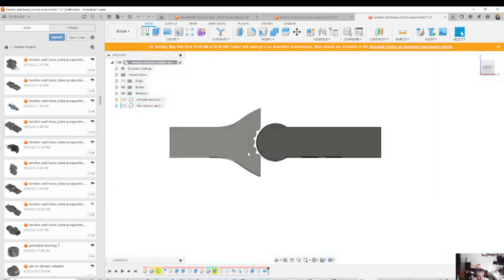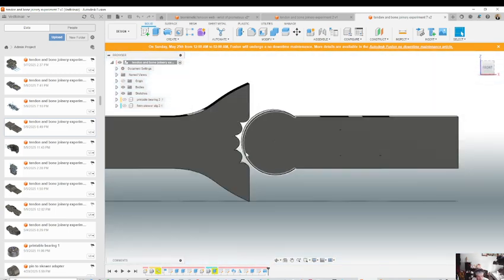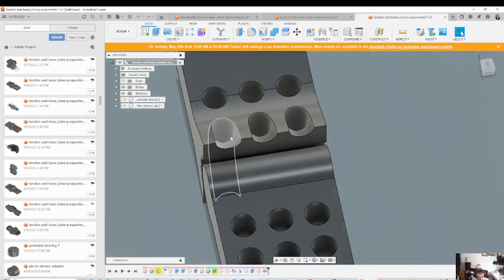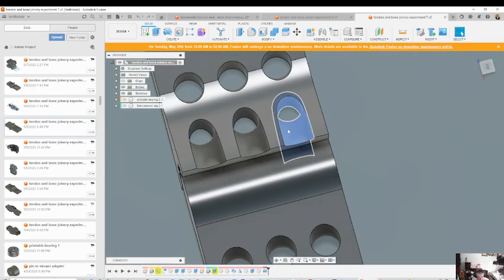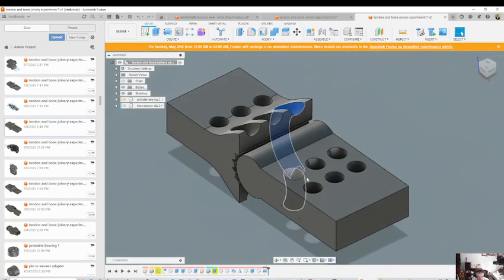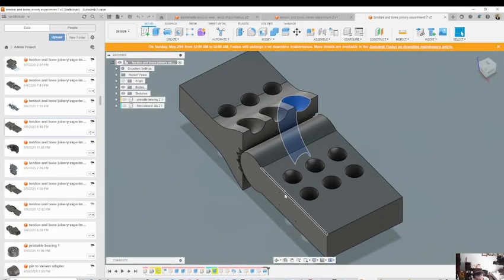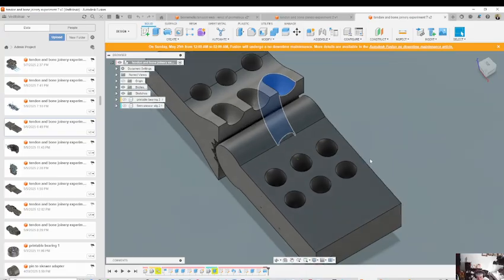So this looks familiar. It looks like the other one. You can see here that there's this fluted intersection, so to reduce the friction. And you can see the channels are much better defined. This is nice and circular. So now I'm starting to optimize it for assembly. So the measurements change as the tips of the fishing lines that I use to assemble those tend to undo themselves, and then it creates this kind of puffed end. And so I adjusted the system so that I would optimize that and make it much easier to assemble.